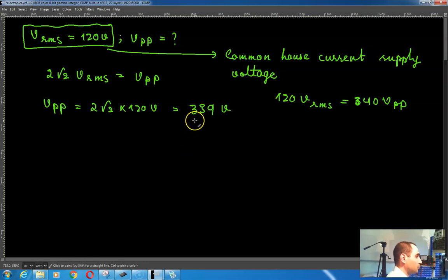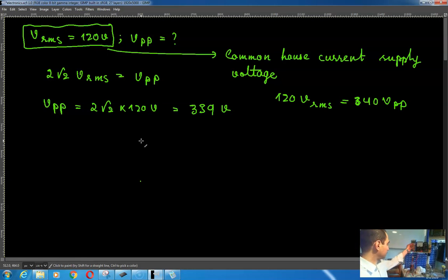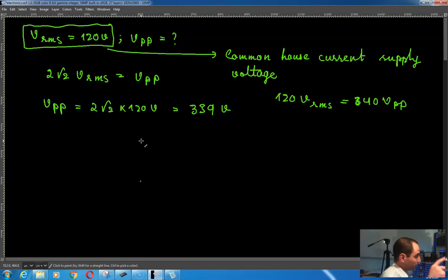So essentially when you connect a simple voltmeter to the wall outlet, and when the wall outlet reads, for example, 120 volts in your house, that means that you're actually measuring the RMS voltage, meaning that the voltmeter, which must be something like this, some voltmeter like this, is essentially measuring the RMS voltage for you, not the peak to peak voltage.